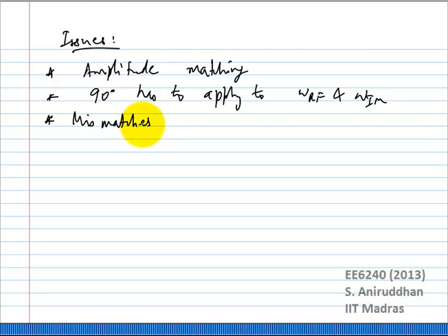Okay? And in that case, we now need to actually define something called the image rejection ratio, because we need to figure out how much of the image is actually getting cancelled. Even if you are considering very narrow band frequencies, you need to figure out how much of your image is getting cancelled. Ideally, it may be 0 dB. Ideally it may be perfect cancellation. You may get 0 of the image signal at the output. But in reality, you will always have some residual depending on the matching.